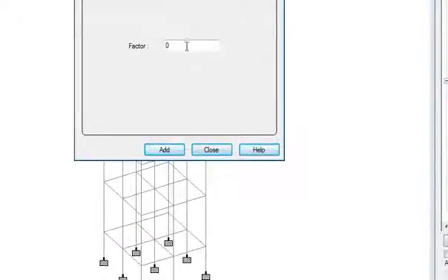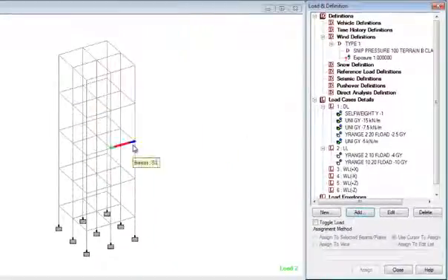And then the exposure. What is exposure? It means the wind intensity acting at a place is acting at a factor of what? It is acting equal to the value that we have calculated, or at a particular fraction of it, say 90% of it is acting or 20% of it is acting. So it is the exposure factor. Let us keep the exposure factor as 1. Add. So now we have got the exposures.